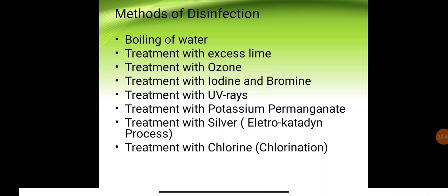And the free chlorine, when it reacts with compounds such as ammonia, proteins, amino acids and phenols that may generally be present in water, forms what? When the free chlorine, that means the hypochlorous acid or hypochlorite ions, reacts with the ammonia, protein, amino acids and phenols present in water, that gives rise to the chloramines.